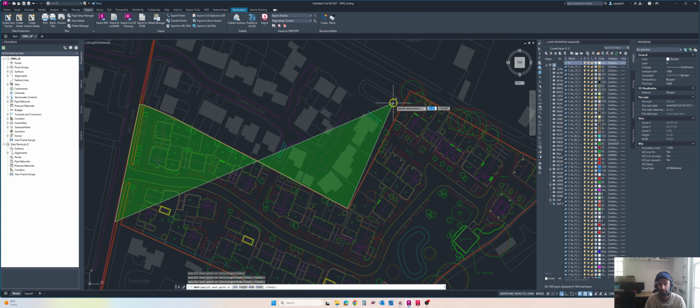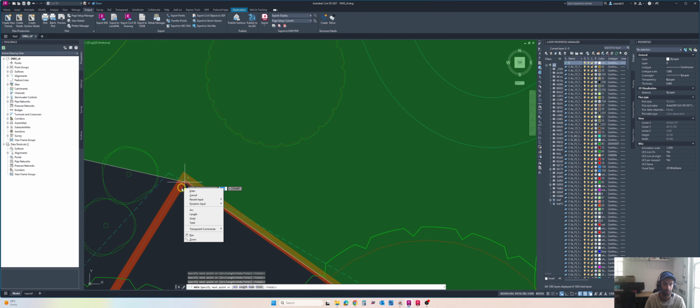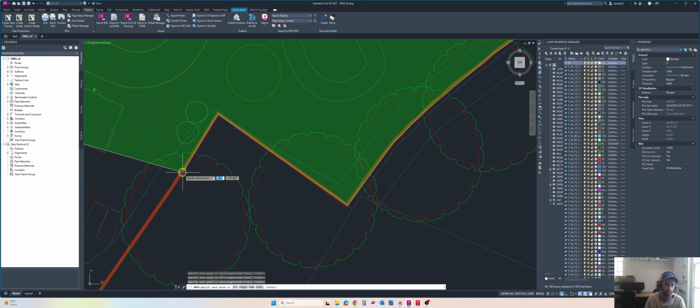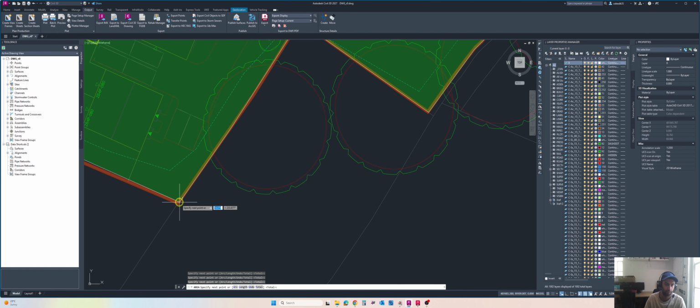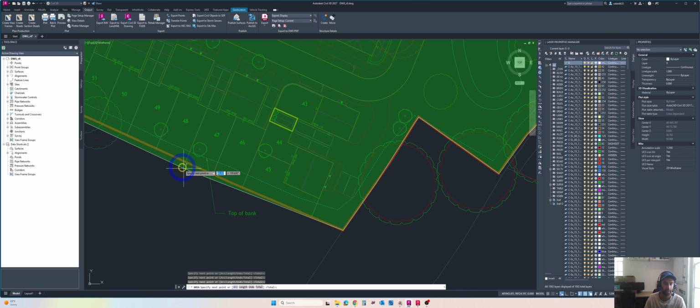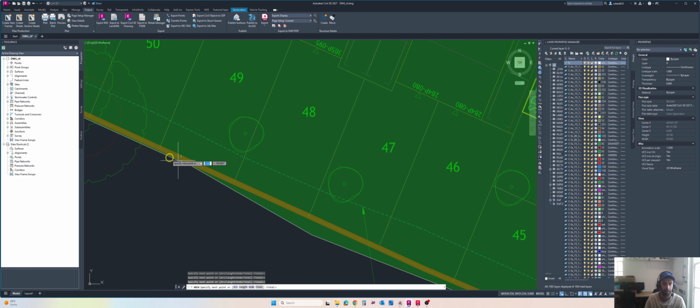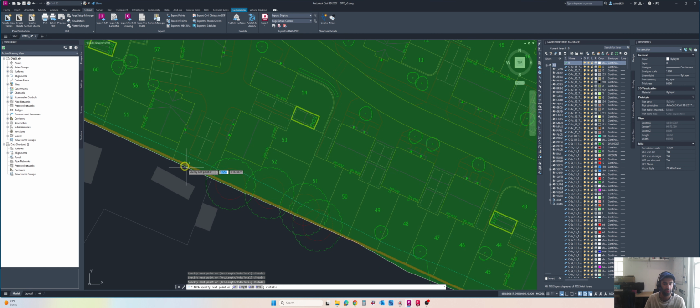This will be calculated for the greenfield runoff, like if we don't have any constructions, and it's a totally green site, only grass, not any developed area. So we have to make sure the runoff from the site isn't more than that.